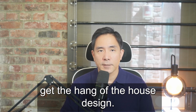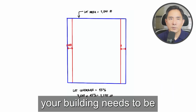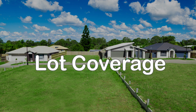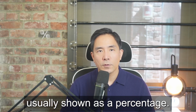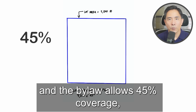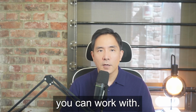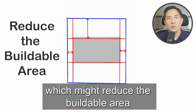Before we go further, let me break down some technical terms to help you get the hang of the house design. Setbacks. This is the minimum distance your building needs to be from the property line according to your city zoning bylaws. Lot coverage. This is the maximum part of your lot that you can build on, usually shown as a percentage. For example, if you have a 7,500 square feet lot and the bylaw allows 45% coverage, that's 3,375 square feet you can work with. But remember, you will need to adjust for setbacks, which might reduce the buildable area.